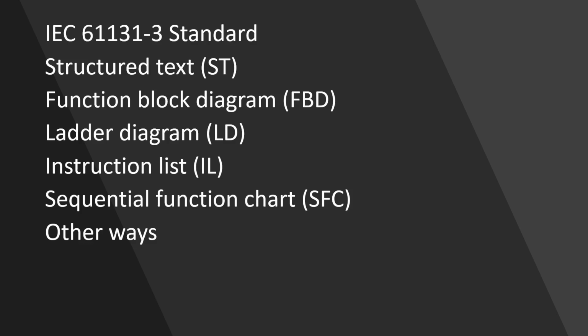Something worth mentioning is CodeSys. I will put a link in the video description about it. But yeah, CodeSys is a German license-free programming tool. It has a text editor for both structured text and instruction list programming, and it has a graphical editor for all three standardized programming languages, LD, FBD, and SFC. On top of that, it has a graphical editor for CFC, continuous function chart. It's somewhat similar to function block diagram programming.